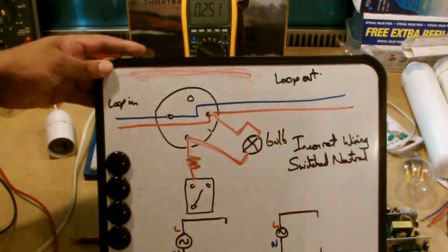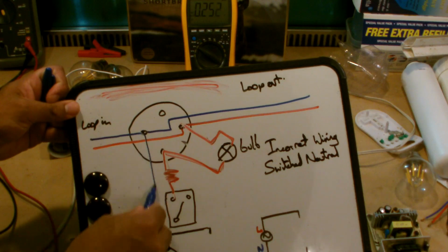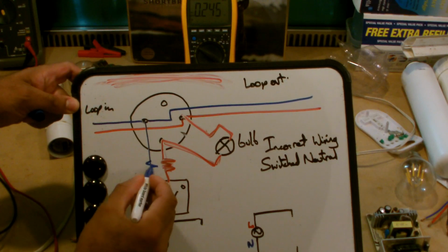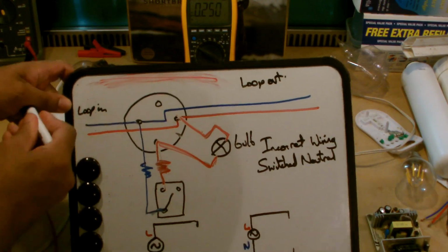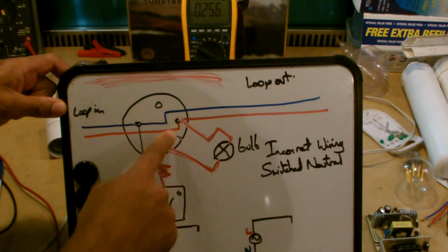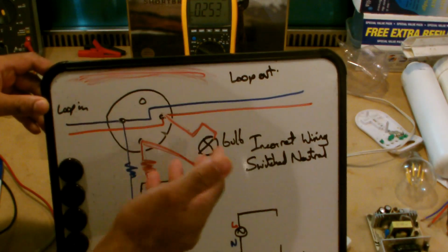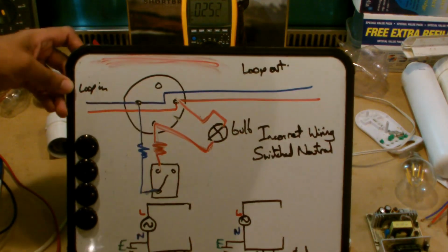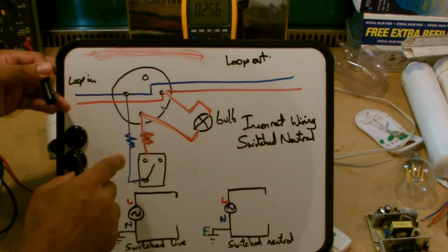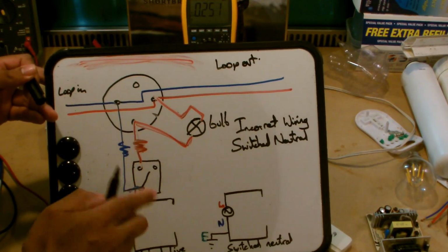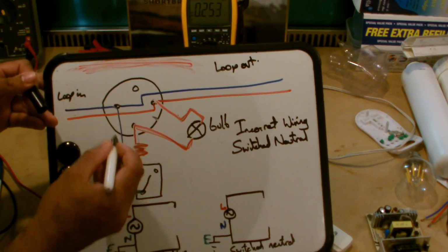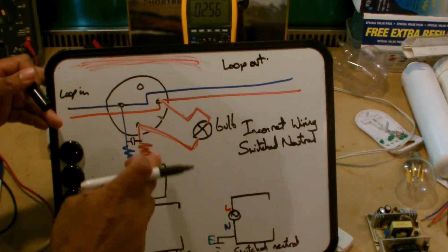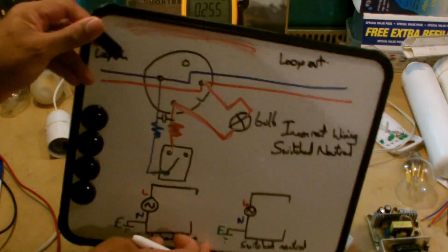So what happens to the other side? Well, that comes from the terminal and goes to the switch, like so. So pay no attention to these bits at the bottom, they'll become apparent fairly shortly. I'll put that concertina in to show that this could be quite a long line. This tends not to be a long line, but if it is very long, it can actually count in your favour. Again, I'll try to explain that in a mo. So what people do is they say that the reason why this is conducting is because there's a stray capacitance here. Say with this long line, the switch and the cable, the length of cable, is causing a capacitance here, and that's allowing enough electricity to go through this and conduct.